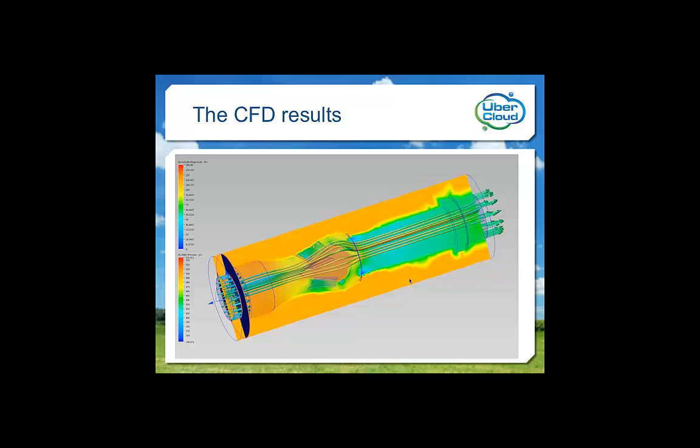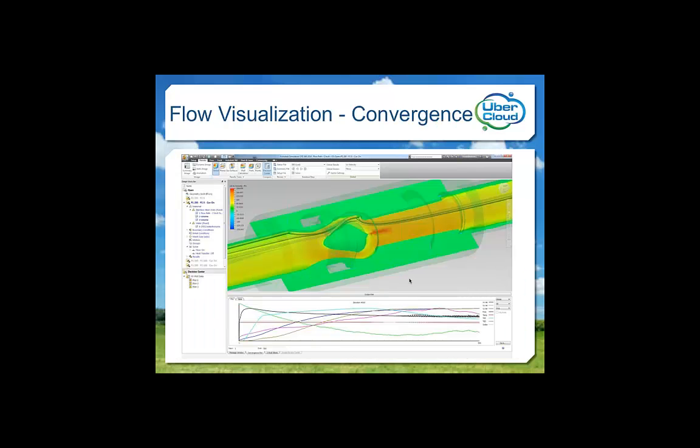So encouraged that turbulent flow simulations with no phase change would be accurate, I eased into choke flow by setting upstream pressure to 200 psi-G and downstream to 0. The solution setting dialog box included an option cavitation on, so I checked it knowing these conditions would cause the fluid to vaporize.